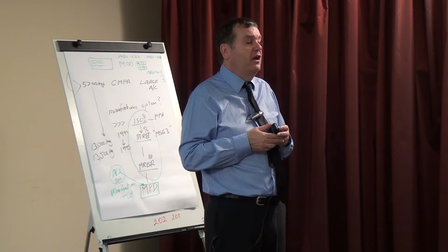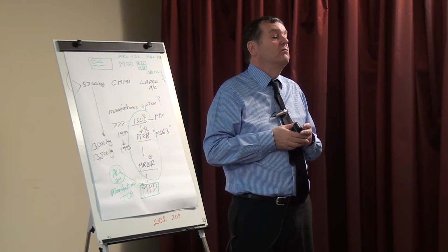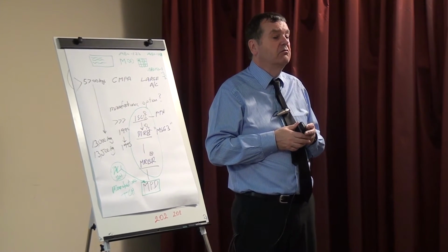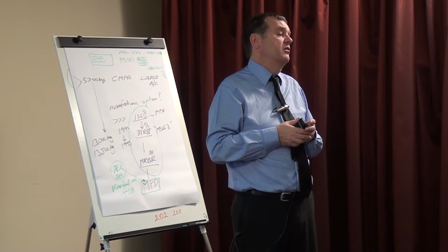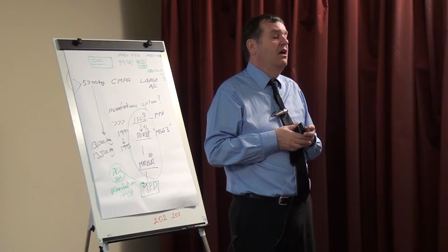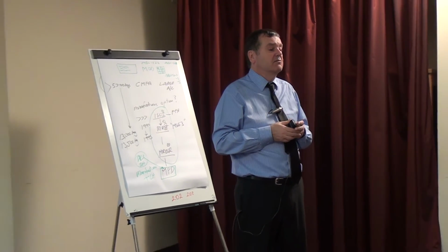So on a 4-engined aeroplane, we have, for example, 4 generators on the engines. If one generator fails, okay, we've got 3 generators. Plus we've got the APU generator. We can live with this. And this became a different way of doing business.